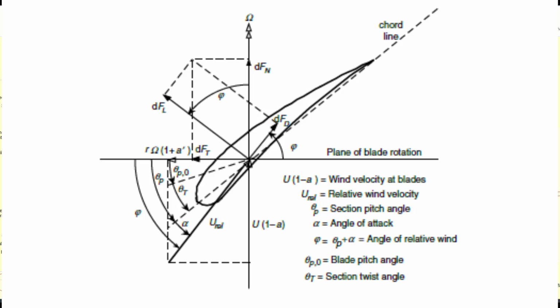Then because of the practicality of the twist of the blade, it's difficult to construct such a blade, so you have to use the coefficient of lift and drag ratios in order to find and identify airfoils that meet those same ratio values with less twist. So that's how you're able to achieve your lift to drag ratio without necessarily having a wide range of twists for the wind turbine orientation in terms of the cross section. So a wind tunnel exercise will help you to achieve that.